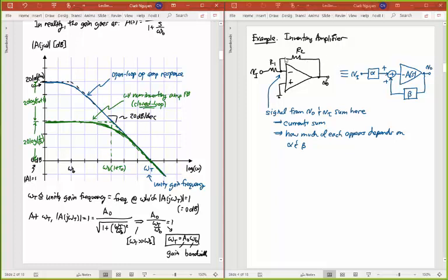Because there's some summation of currents here in the block diagram, I'm calling this a summer, and both of these are coming in with pluses here. The negative feedback is coming from the actual minus terminal of the amplifier here. If you go around the loop, you'll see that this is indeed negative feedback. We did this in a previous lecture, so I won't do it again. The minus sign here, if I go around the loop and that's minus, tells me I've got negative feedback. But this alpha here, which is the transfer function going from the input to this minus terminal, which has to go through R1, is now a new thing for us.